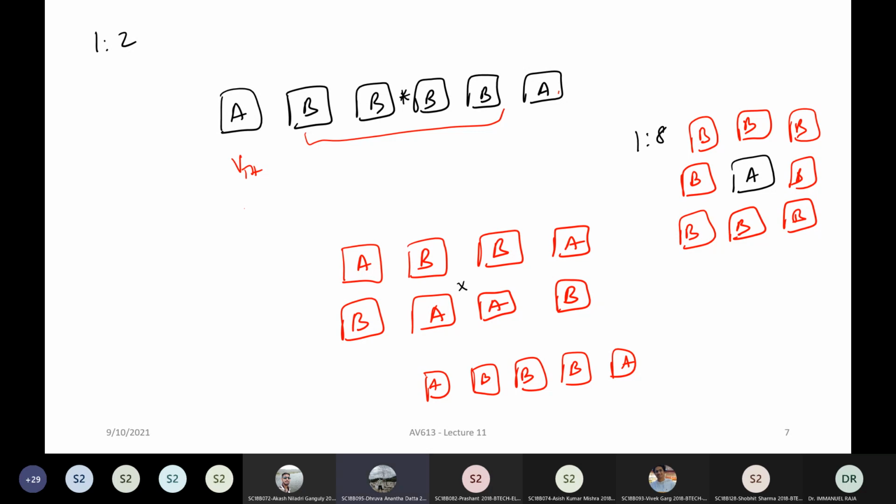Okay. You want to make sure that, again here the VTH of B1 will be in this order, but then the average VTH of the whole B device, right? The average of A and the average of B will be the same, which means you'll get the same current. Okay, sir. Yeah. All right. So this is what, yeah, someone else had a question. The gradient may not necessarily be linear, right? You're right. It may not necessarily be linear. It can also be non-linear. But I think what they have found experimentally is that taking care of the linear gradient itself solves the problem to a large extent.